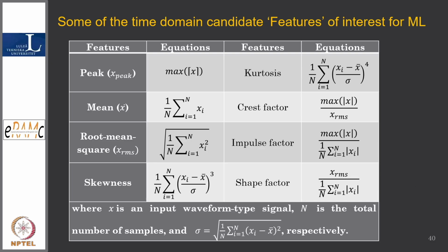What we are discussing in this slide is what kinds of characteristics the data should be used for: what is the mean of the data, what is the peak value of a parameter, and if it is a frequency domain signature, which frequency dominates; if it is a time domain signature, at which time it happens and how frequently it happens. So in vibration, time domain and frequency domain data are used depending on the situation.